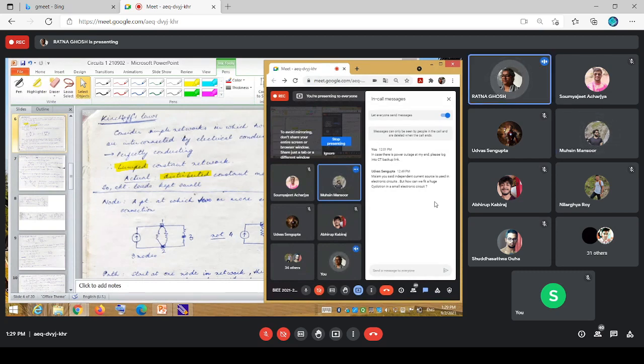Yeah, I agree. What you are saying in essence is, had you started with the distributed constant representation, then it would have been a much more complicated thing, which you would have approximated down to a KVL or a KCL. Yes, ma'am. Okay. So instead of doing that, what people have done in electrical is they've directly taken the approximation in the representation itself. Instead of a distributed constant representation, we normally talk of a lumped constant representation. And as a result, we have the simple KCL and the KVL that we directly talk of.